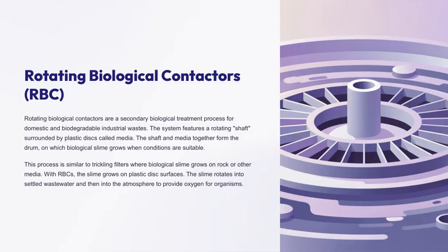Rotating biological contactors, or RBCs, are a really interesting secondary treatment option for both domestic and biodegradable industrial wastes. The core of the system involves a rotating shaft that's surrounded by plastic discs, which we call media. Together, the shaft and these discs form what's known as the drum.